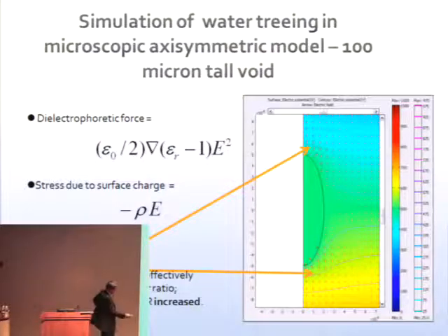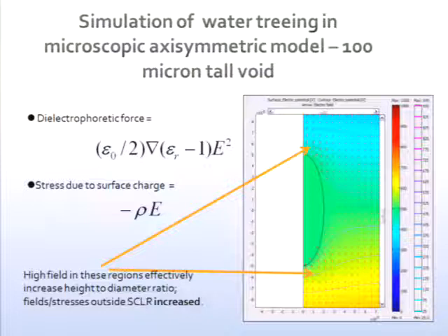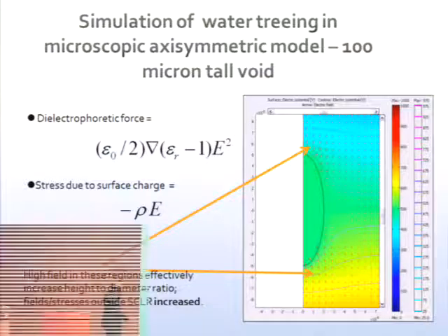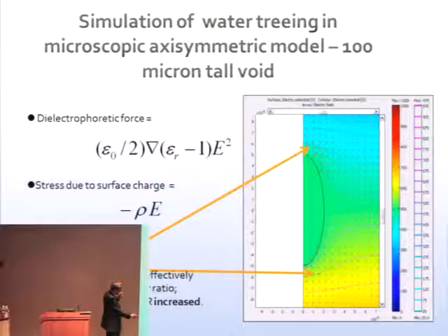That means that where I've got a concentrated electric field here, the conductivity will be much higher than it is out here someplace. What that does is effectively elongate this ellipsoid. Well, at the ends, the maximum field is limited by the high carrier mobility. Yeah. The phenomena limiting the current I don't care about for the moment. I'm suggesting that this gives this region a much higher conductivity than out here someplace, which has the effect of elongating this region of high conductivity, and therefore it enhances the stress.